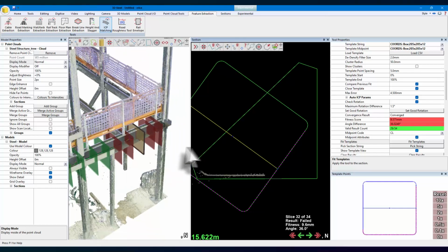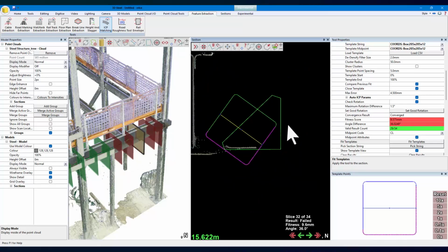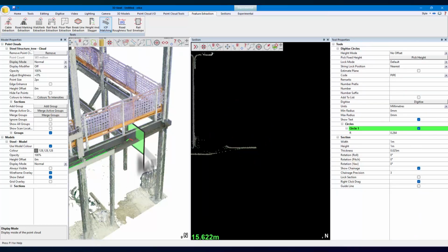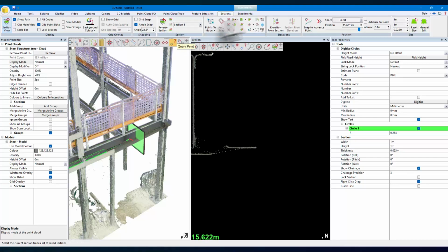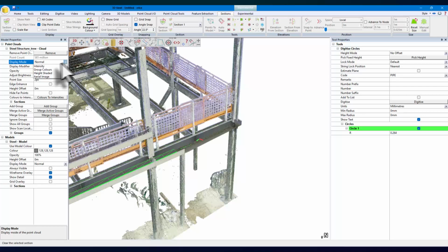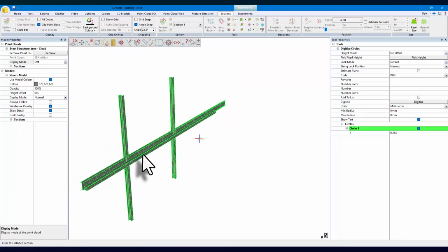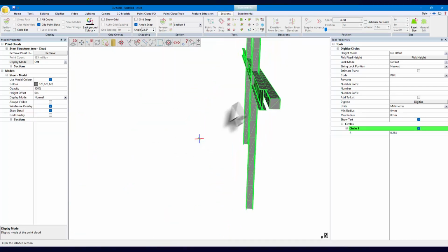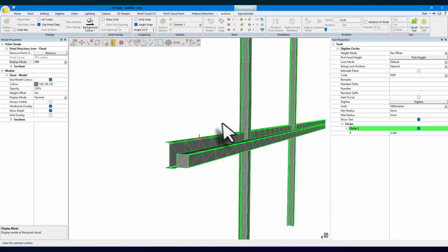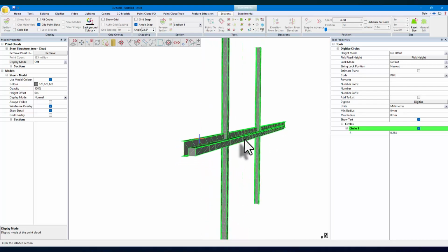When this actually becomes a primary release, there will be a tool to essentially extend the end. So if the data does that, you'll be able to just drag it out further and assume that's what it looks like. But obviously they failed, but for now that's fine. So we're going to hit extrude, and then I cancel everything, delete the section, and turn the point cloud off. There we go. Okay, and that's fully exportable to DWG as a 3D mesh, or to IFC or to OBJ.